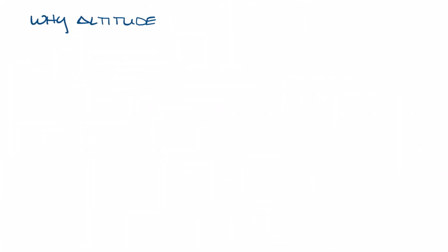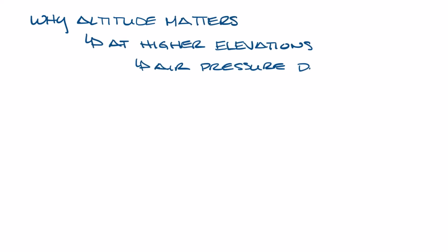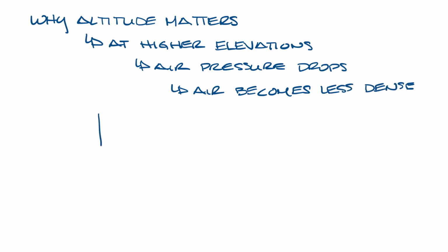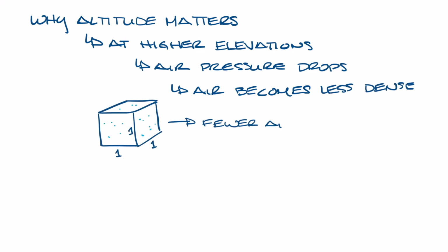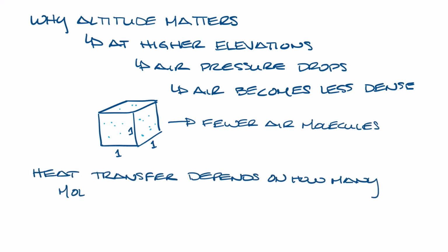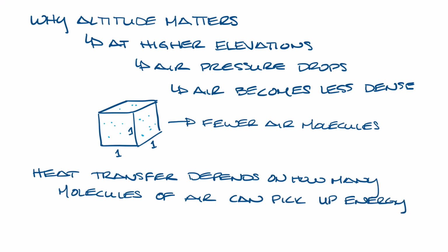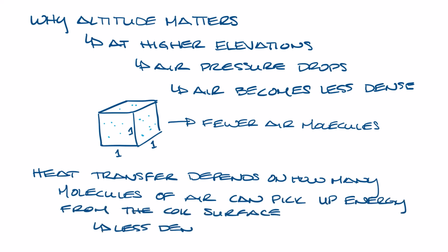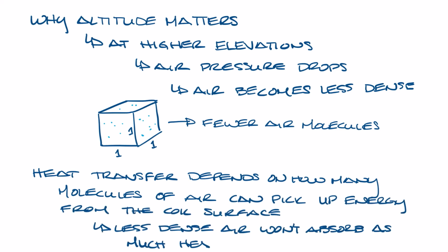First, a refresher on why altitude matters. At high elevations, the air pressure drops and the air becomes less dense. This means for every cubic foot of air, there are simply fewer air molecules. Since heat transfer depends on how many molecules of air can pick up energy from the coil surface, less dense air won't absorb as much heat.